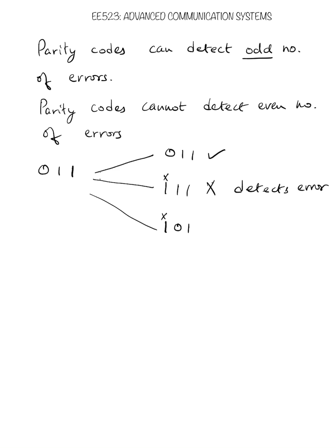So there is an error in the first position, there is an error in the second position. However, in this case with 2-bit errors, the receiver or the decoder will check if the number of ones is even, because we used even parity for our communication. When it checks, it finds that the number of ones is even, and therefore it thinks that there is no error, so it fails to detect the errors, right?